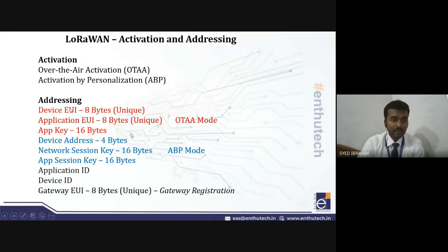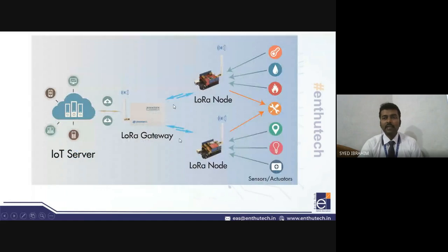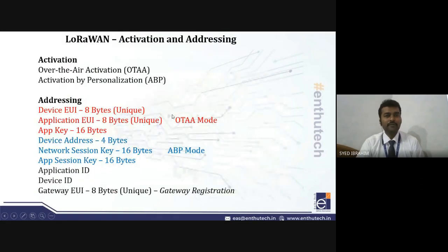And we will be using three different pieces of information from the cloud. We are connecting our application to the cloud through a processor and gateway. It is as simple as that. Over here is the application, and here the cloud. So we are going to get the information about our application on this cloud, and it is connected through a processor and a gateway. This processor sends a radio frequency signal which can only be received by this LoRa gateway, and this LoRa gateway sends the signal to the cloud. All right, this is the basic of this LoRaWAN architecture.